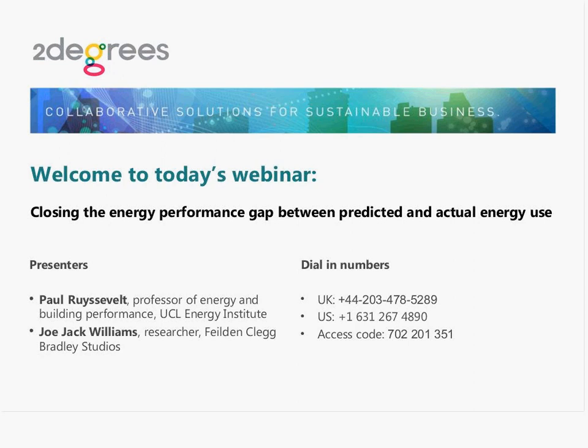Okay. Well, at design stage, if it's a non-domestic building, you will typically have some sort of design stage prediction that will often break the energy use down into component parts, so that you can enter that into the platform. It will not typically include the unregulated energy uses of computers and IT and so forth, and as I was just mentioning, some engineers now are going the extra step and attempting to model or calculate those unregulated uses as well to get a better overall prediction.